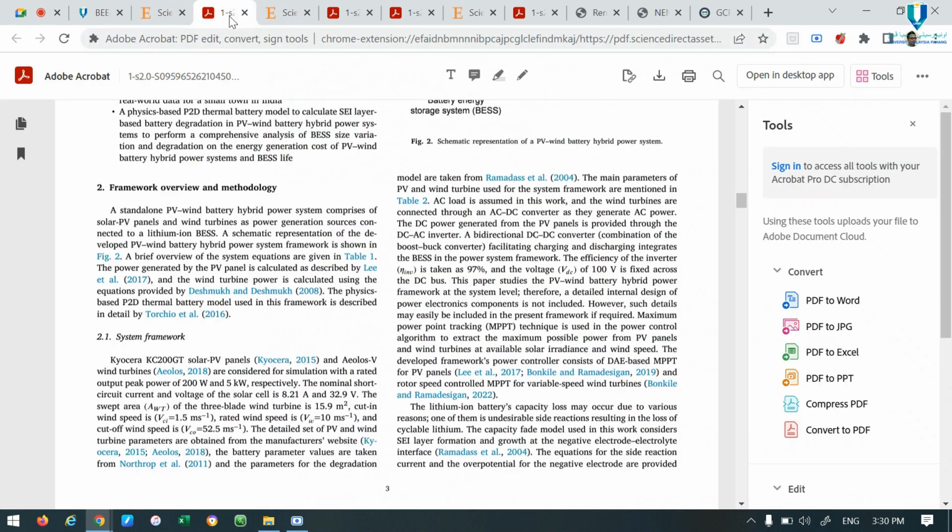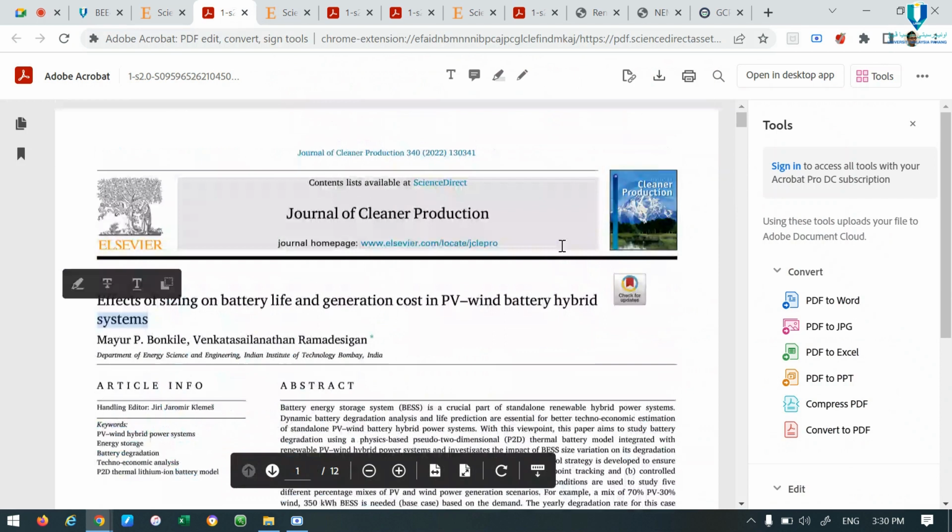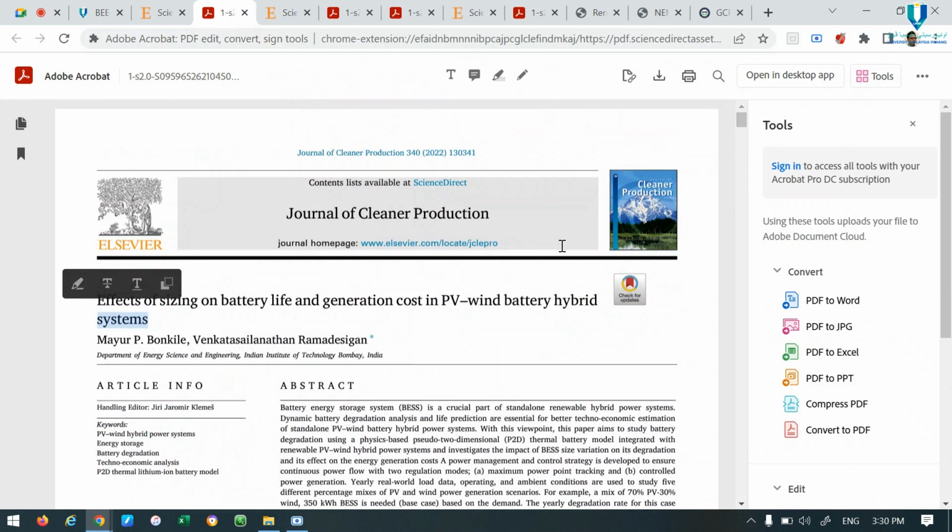They have the diesel also. Sometimes they have the diesel as the backup, I mean the genset. For a small scale, maybe 4 kVA or 6 kVA of backup, that is the last resort. During a thunderstorm, confirm the PV will rarely generate any energy. At the same time, wind is also maybe not applicable because the wind from the storm is very strong. So there is a limitation of the wind turbine. The limitation depends on the specification.